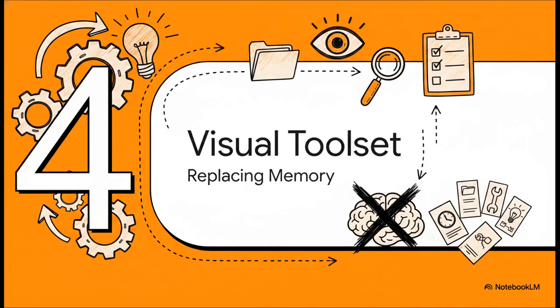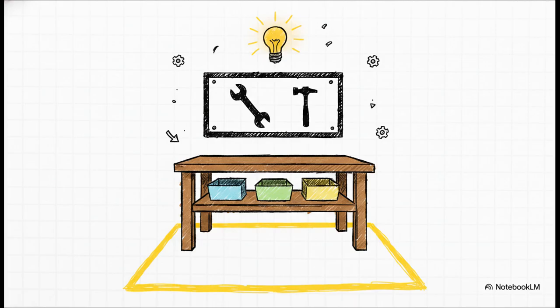Section 4. The Visual Management Toolset, replacing memory with cues. The foundational Seiton toolset relies incredibly heavily on passive cues. We want to design a space where literally nobody has to rely on their memory to know where things belong. We use point-of-view storage frameworks to keep things exactly where the work actually happens. We use shadow boards to create silhouettes for tooling. We use painted floor markings and standardized color coding systems to clearly demarcate different zones.